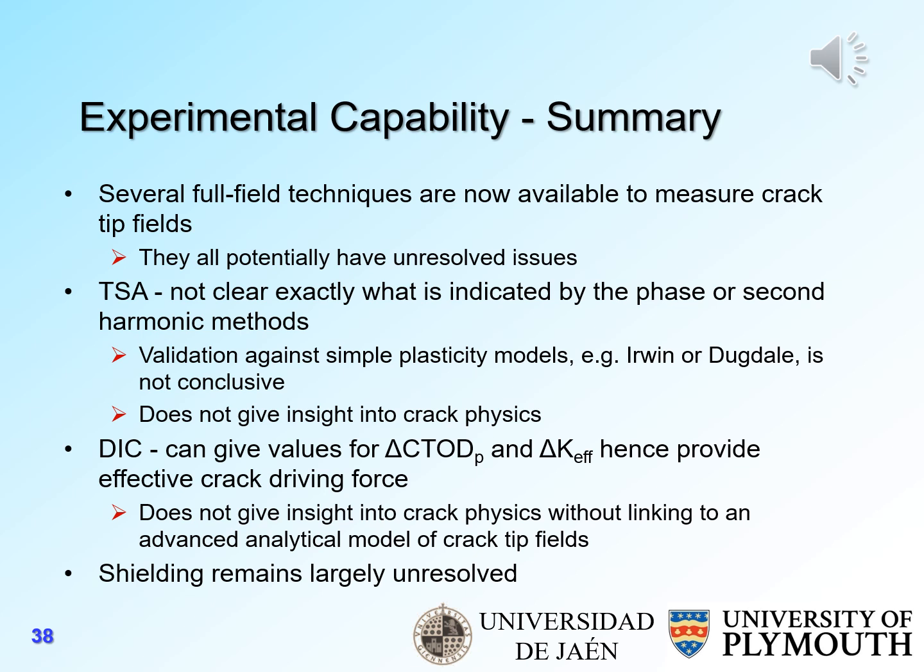So summarizing this very brief overview of several full field techniques, there are now some very advanced techniques available to measure crack tip fields, but they all potentially have unresolved issues. With TSA, it's not clear exactly what's indicated by the phase or second harmonic methods, and validation against simple plasticity models, e.g. Irwin or Dugdale, is not likely to be conclusive. Equally, TSA does not give insight into crack physics and the underlying crack growth mechanisms.